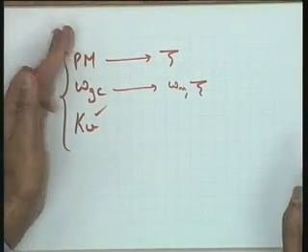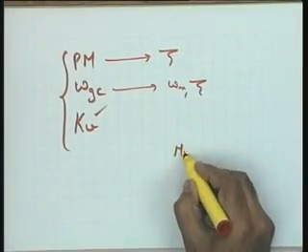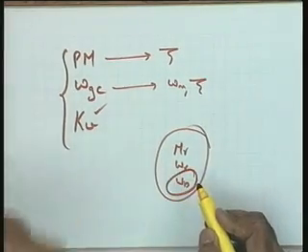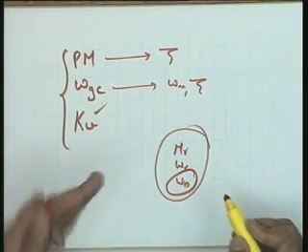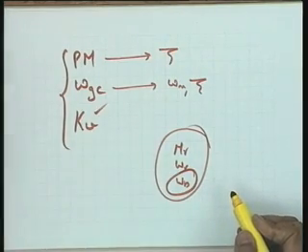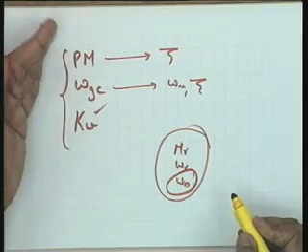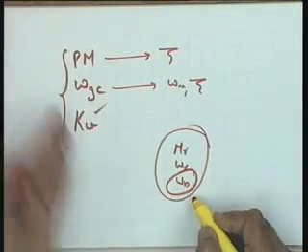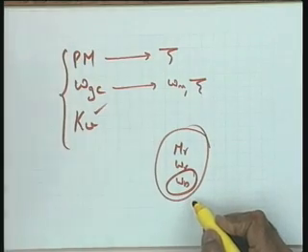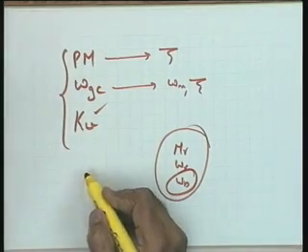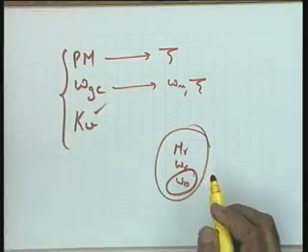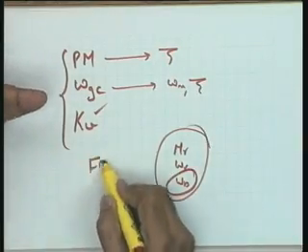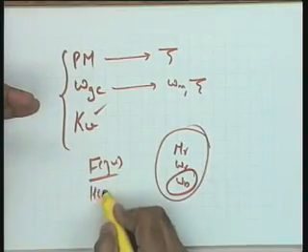Once I have done this, I want to see whether the requirements on Mr, omega r, omega b, if any, are satisfied. Naturally, omega b requirements may be specified by the user. Partially I can take the help of the CAD software and immediately check the corresponding value of omega b, whether it is satisfied or not. Because the graphical help which I get from the approximations is not available from this type of manipulation, F(jω) over H(jω).